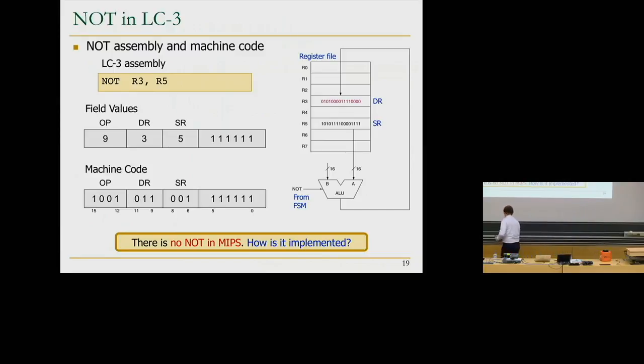If we do this very quickly, I don't want to spend a lot of time on this, but this basically goes back to Boolean algebra. If you want to compute NOT of x, you can write NOT of x as NOT of x and NOT of x. And De Morgan's rules tell you that that's the NOR of x. Essentially, you can use De Morgan's laws, and you can use all your Boolean algebra to implement something that doesn't exist.